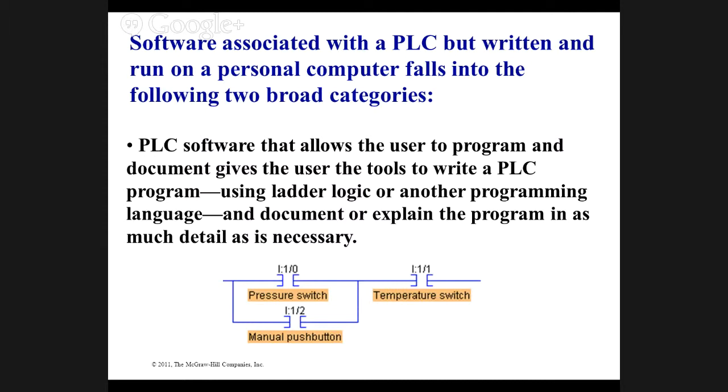The PLC program is required to run the PLC. The documentation is filled in on your PC, basically. Sometimes the program's worthless without documentation. It can be so big and convoluted that without documentation, and without prints to make your own documentation, it's just not very good. So documentation is very important when you're programming a PLC.